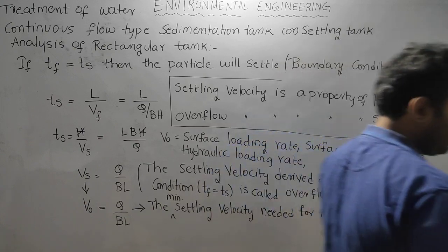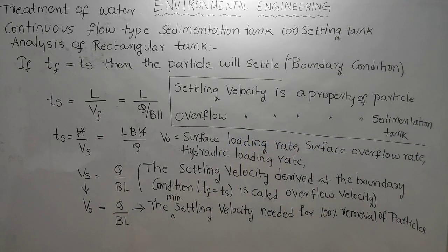For 100% removal of the particle, this is the minimum settling velocity needed. That is nothing but the overflow velocity.